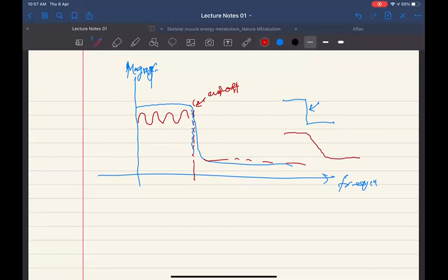but it's not like this, but it is some inclined plane, something like that. It's like when you stop your signal, part of the unwanted signal is still transmitting, and finally after some time that signal is completely cut down. So this cutoff point is not working very efficiently here. And if you want to make it steeper like that, the blue one, then it means that you have to make it more expensive, or you have to put some more components there so that it can be steeper. So then you have to put some more resources there, right?